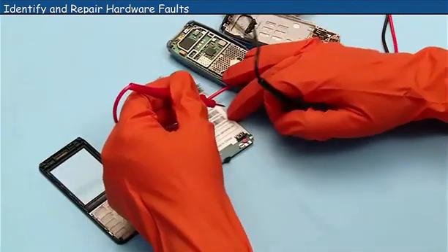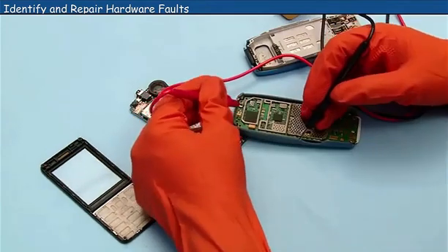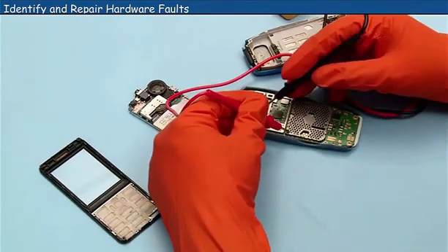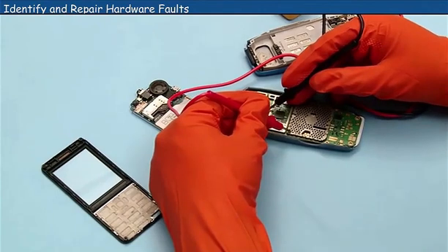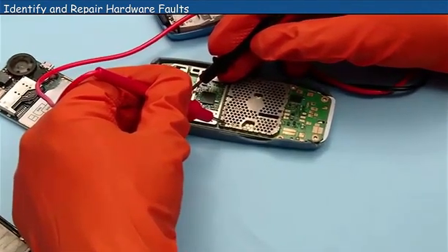To check the battery pin connector in interference type, take a multimeter with the same ohms range. Check for continuity. If a beep sound is heard, then there is a fault in the battery pin and it needs to be replaced.